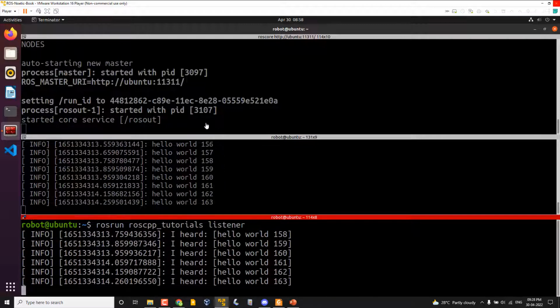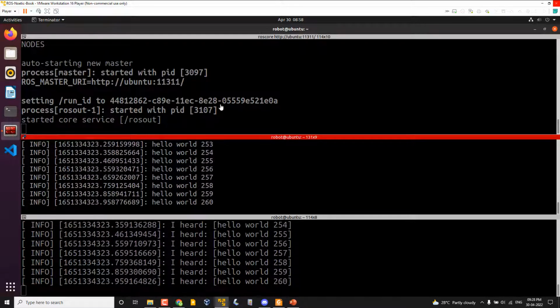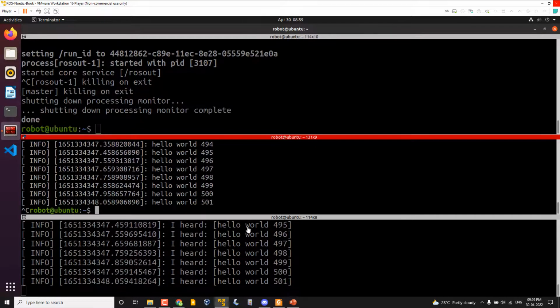While working with ROS, you will have some confusion. Some of you start roscore, then in order to start the next command, they close roscore and then execute the program in the same terminal. So I prefer a terminal application called Terminator. I'm giving the command to install Terminator on your PC, simply sudo apt install terminator. Maybe I can show you that.